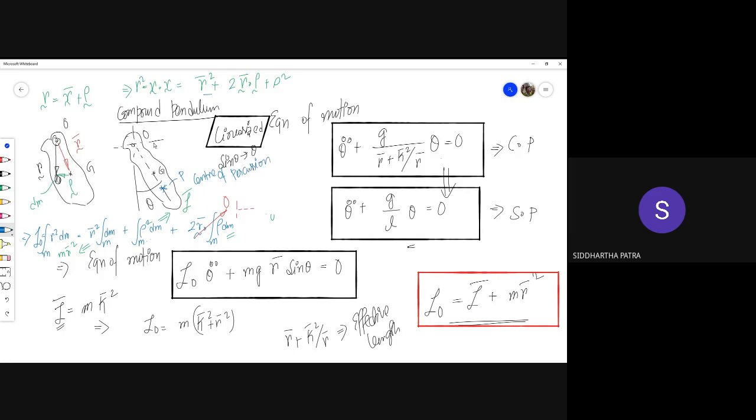Okay. So up to the center of mass, it is R bar. But if you proceed along the same line, the center of percussion lies below the center of gravity or center of mass by how much? Kappa bar squared divided by R bar, which is a positive quantity.